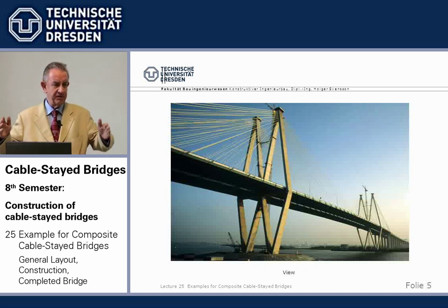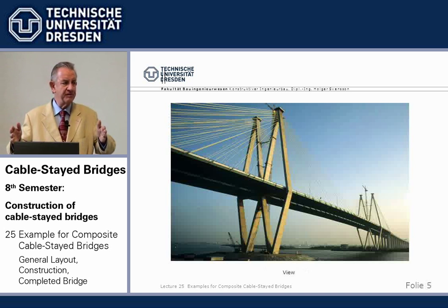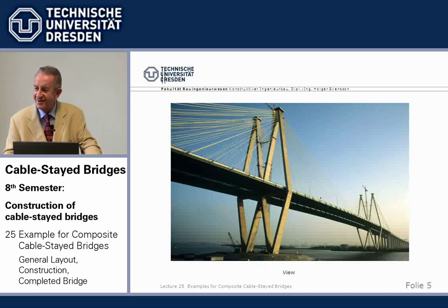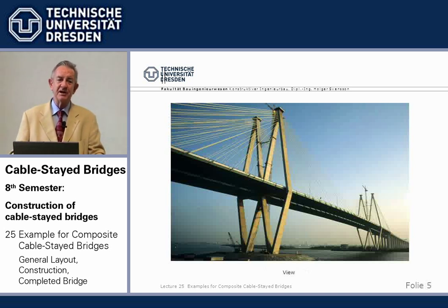Now, using stay cables at the outside, we have cross girders with 50 meters, which is already a sizable small bridge. Consequently, when we did our first design with 2 cable planes, we found that the amount of steel required in the beam in the longitudinal direction for the main girders was in the same range as the steel required in the transverse direction, which is highly unusual.